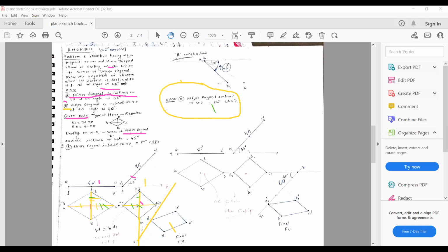This means the way we have done in projection of line, finding alpha and beta, a similar thing you have to do here, okay? And with the beta angle, which you will get later on by following a certain construction process, that angle you have to take instead of this 30 degrees which has been mentioned here, okay? So you have to find out beta now. You all studied projection of line, I repeat, and you are aware of alpha and beta, when they are needed and when they happen, because the line is inclined, not parallel to any plane, in that case, okay?